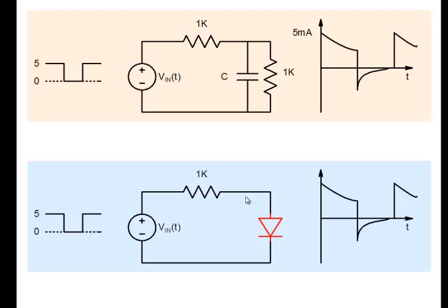So now what happens is, think about it. I have a capacitance here, which is depletion capacitance and diffusion capacitance. Depletion capacitance doesn't matter in the forward bias, because diffusion is much larger. So I have this diffusion capacitance which is all charged up, right? Now when you make it 0, this diffusion capacitance has to discharge. And as it discharges, it pumps in all this current here.